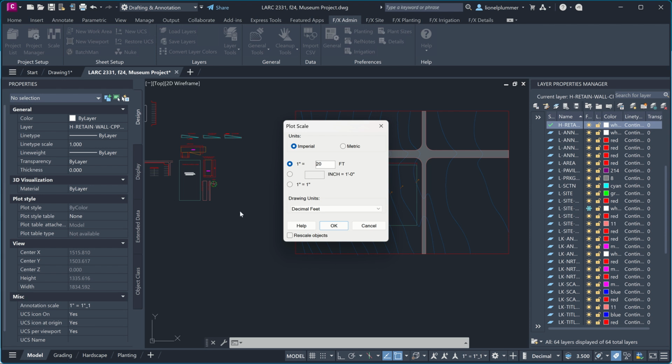That's why we set scale, because everything in CAD, like I said, these trees are going to be the same size whether you're using architectural inches or whether you're using light years. The whole reason we have scale is so human beings can read what we've drawn.